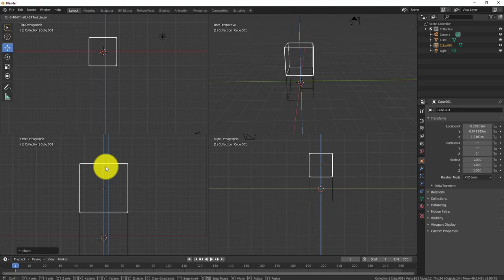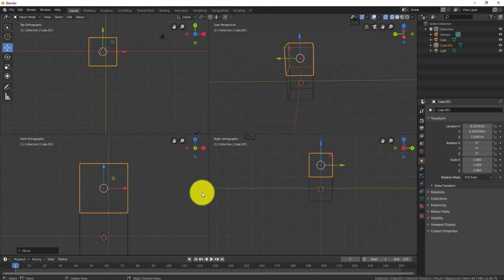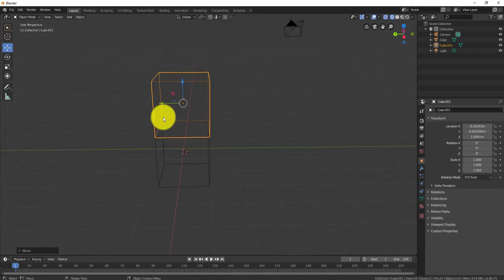Okay, so my challenge to you is to create a stack of 3 boxes that are perfectly on top of each other. The bottom box should be bigger, the second box should be a medium size, and the top box should be the smallest size, and they should be rotated, kind of have different angles around the z-axis on top of each other. And make sure they're touching. So if you want this view, you can do that. If not, you can just use perspective view, which is Control-Alt-Q, and you can go back into that view. Okay?